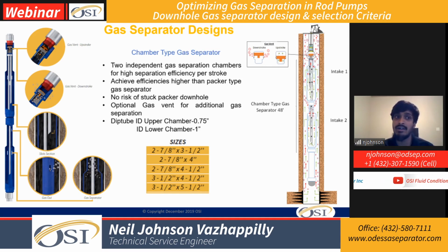The other very critical design parameter for this chamber type gas separator to work is the ID of the dip tube in both of these chambers. I'll talk about why we need that. Overall, having two individual separators, if we can get a good enough fluid distribution in both chambers, we're going to get a much higher separation efficiency in every stroke. We separate individually in both separators, giving us an average gas separation efficiency much higher compared to a modified Mother Hubbard style.